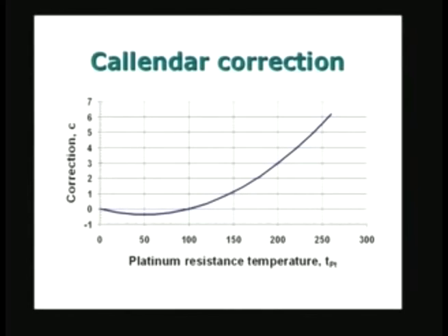What is the advantage of this method of calculation? So, what I will be doing is, I will be calculating T PT using the linear relationship and then calculate the corresponding value of the correction using the linear temperature which has been calculated and putting into the equation for C, and then I will be able to calculate the temperature without much difficulty.